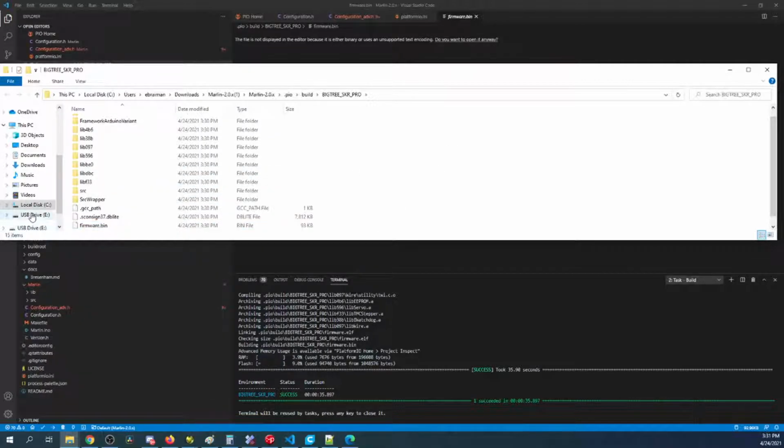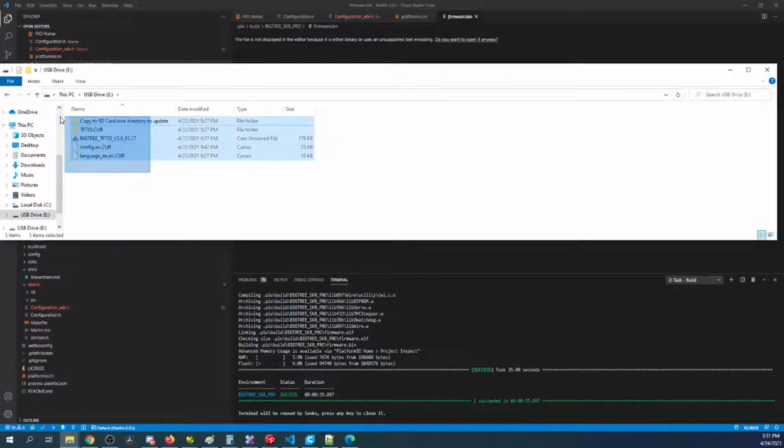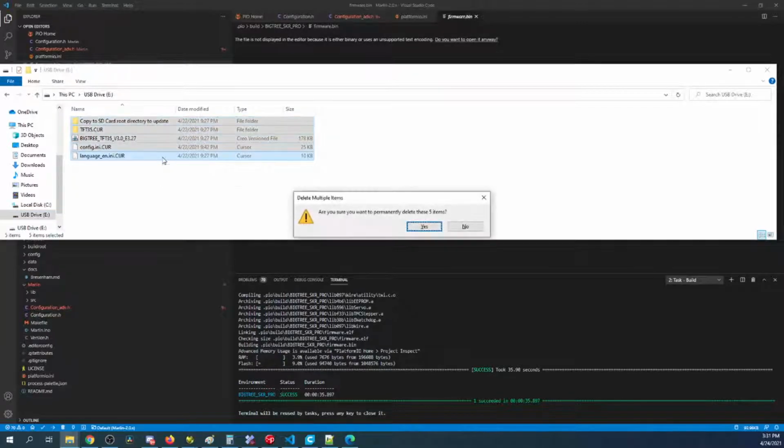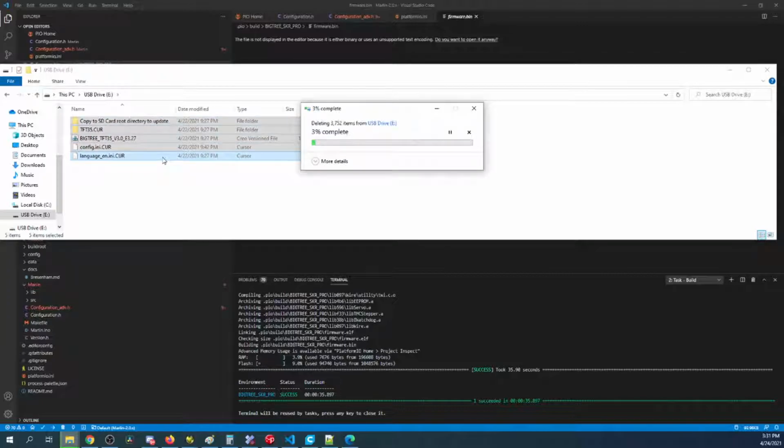Now you have a new configuration, so you're probably going to see something that says firmware.cur in capital letters. That's the firmware that is currently loaded on your drive. So you can copy that off and store it someplace, but if you ever need to reload from that, you can just basically copy it back onto your drive, and you can then say firmware.bin in lowercase, and it'll reload like normal.